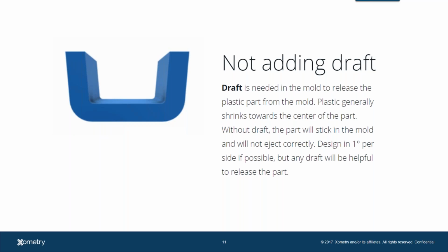This is very, very important from a practical nature, because you need this to release the part successfully from the tool every single time. And because when we talk about injection molding, we're not talking about 5 to 10 pieces. We're talking about 5 to 10,000 pieces. You want to make sure that you're incorporating draft features to reduce anything that causes either catastrophic failure, you know, pinch and mold, or something that can deteriorate a part over time as you're molding.